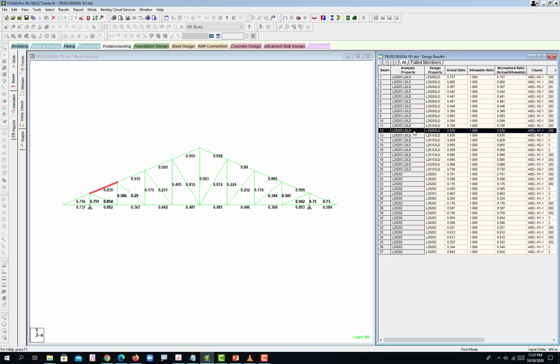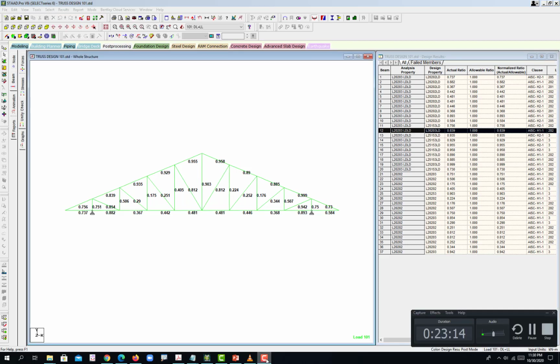Then member 12 is different again: it becomes 3 by 2 by 3 out of 16. So either you choose just one. Be careful on this select optimize of STAAD. Okay, so that's how you design your steel truss by applying method 2 of the analytical procedure of the NSCP.